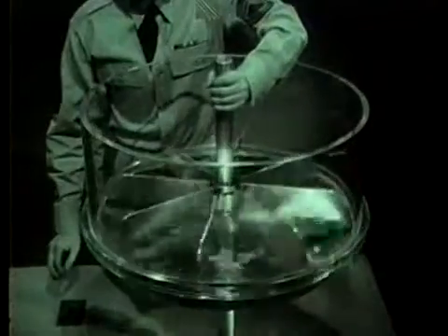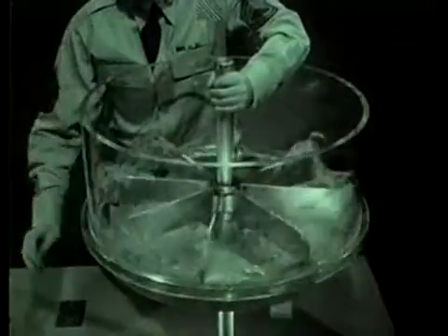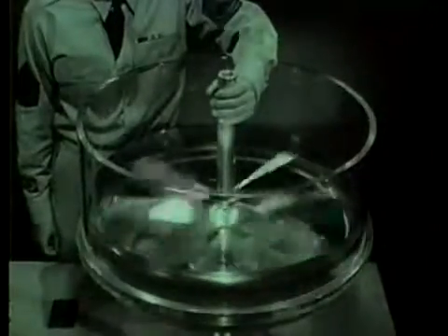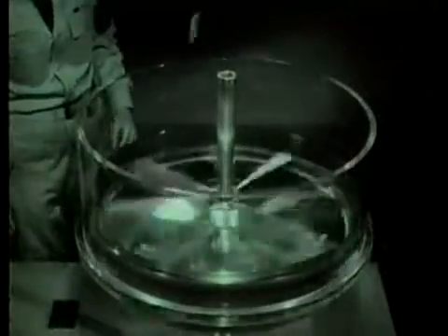The shaft, which has a marker to show rotation, can be likened to the drive shaft of a vehicle. The upper set of vanes doesn't revolve at first because the bowl isn't imparting enough energy through the oil to overcome the resistance of the hand holding its shaft. As the speed of the bowl increases, more energy is transmitted, causing the upper set of vanes and its shaft to revolve, despite the load exerted on the shaft by the hand. This pressure of the hand can be likened to the load the engine must move. The lower set of vanes is called the pump, the upper set, the turbine.